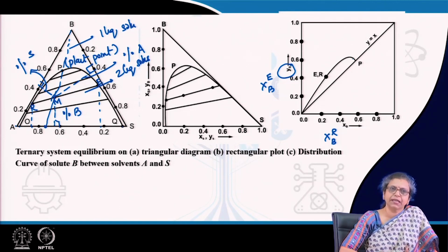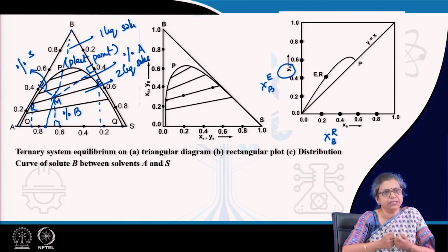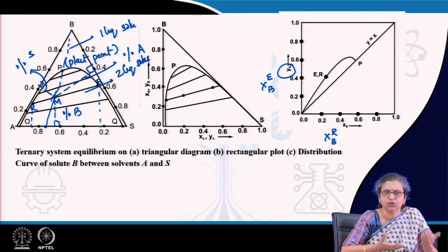Very frequently they are expressed in terms of alpha, which gives you the relative ease of separation. And just like we have equilibrium ratios or the K values for distillation, we have distribution coefficient for the liquid liquid extraction cases, and just like Pxy, Txy, Xy are important for distillation, the Pi versus Xi curves are important for absorption.